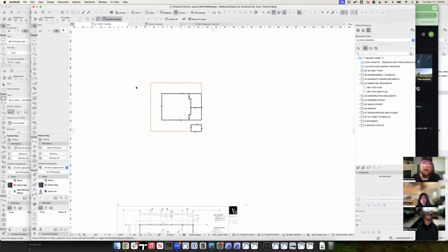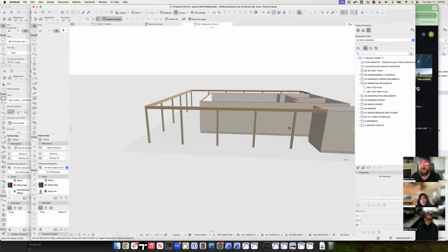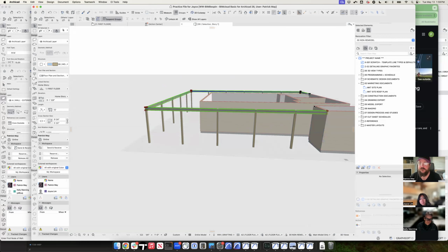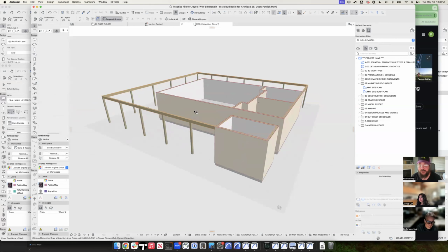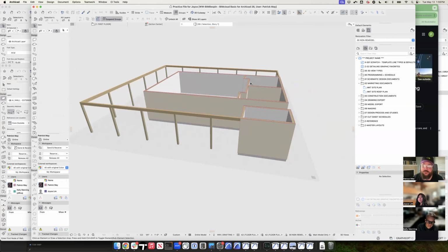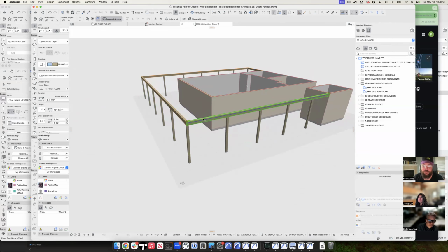All right, so now I want to take a look at my 3D model. I'm going to select this, and like we talked about yesterday, if I want to see a selection, I hit F4, and there's my beams, my columns, my walls. And this is where following through and adjusting things as you go is really helpful, not getting pigeonholed. Just because we're only looking at 2D floor plans, maybe it's an early SD and we only need schematic plans. If that schematic plan includes a model that's halfway clean, that means that when we get into mid SD and we start to look at renderings and elevations and stuff, we're not scrapping it all and starting over. So a little bit of time and consideration ahead makes modeling down the road a lot quicker and cleaner.